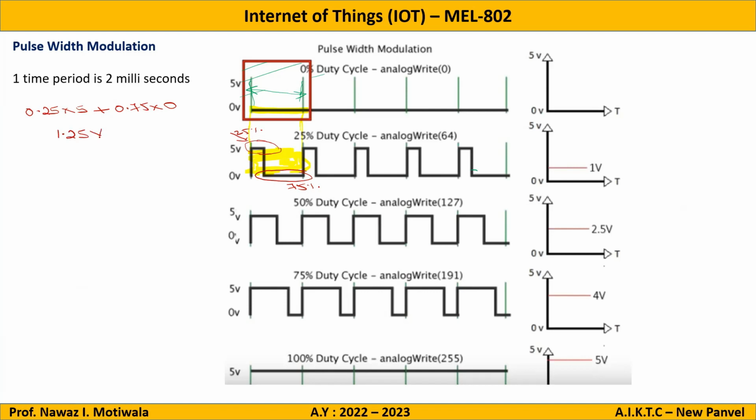So instead of 0 volts in the first step, the average voltage passing in one duty cycle is now 1.25 volts. If 1.25 volts is passed in one duty cycle, the LED will glow with that particular voltage. Now, how much brightness will there be? As we have said that it is working only for 25% of the time, the LED will also brighten by only 25%.